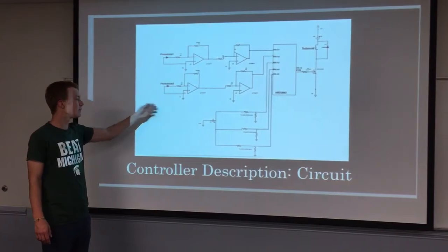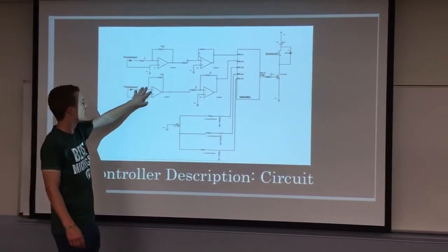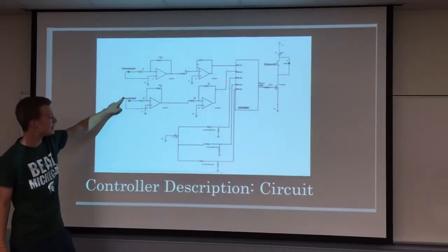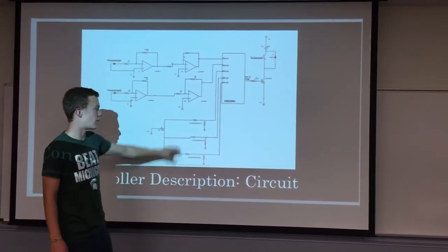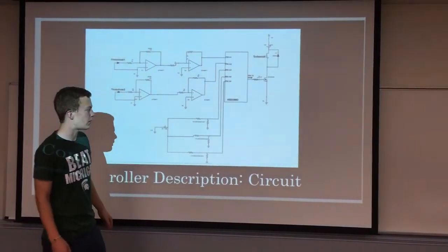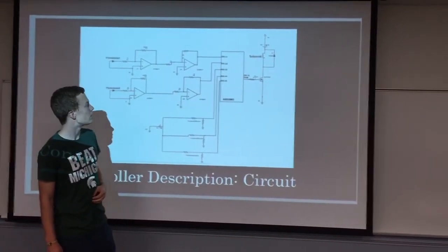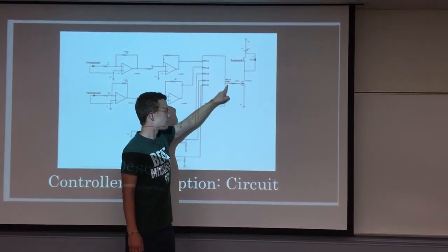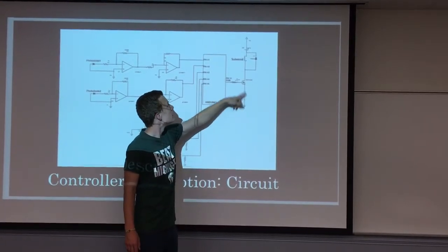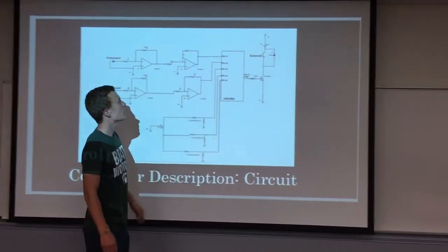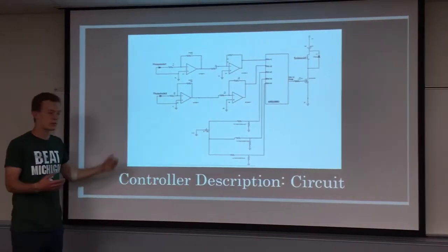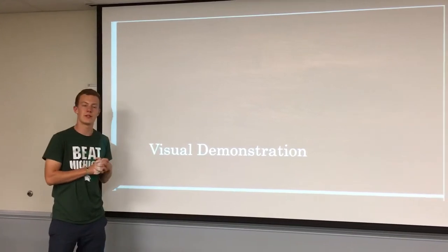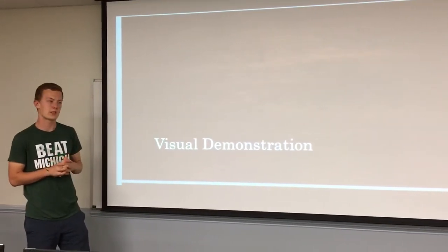In the circuit diagram, here we have the op amps that amplify our sensor signal from the photodiodes over here. We have our 3 potentiometers where we use 2 to read KP and KD. This is our MOSFET, our PWM output, ground, and the solenoid. This is pretty much the setup. And now we'll show you a short video of how our system is actually working.